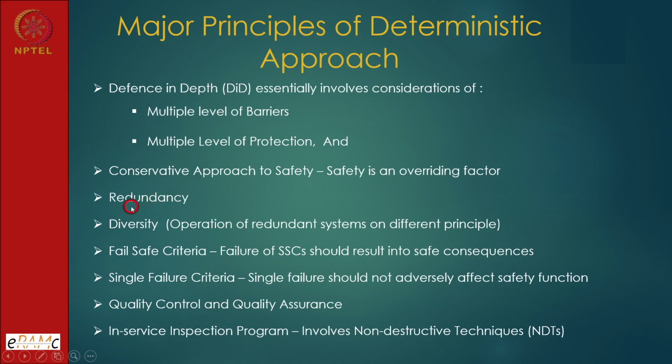So, redundancy, and as if that was not sufficient, diversity also forms part of the defense in depth or deterministic approach core principles. What is diversity? One safety function which is being carried out by a certain system, there will be one additional system wherein the principle of operation, right from the scientific fundamentals, will be different.